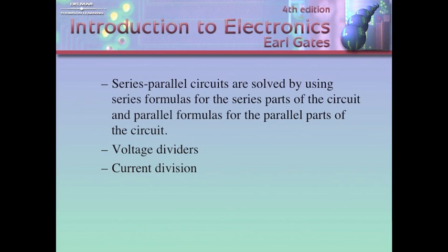So what we're going to do here is connect another load, which we could represent with a resistor here. And this is going to be a 5-volt load. The load we're going to connect here off of B is going to be a 12-volt load. And then this up here, we're just going to use for a voltage divider to get rid of the other 12 volts from the 24 volts. So I'm actually connecting two loads to this circuit. Do you agree with me? Okay.